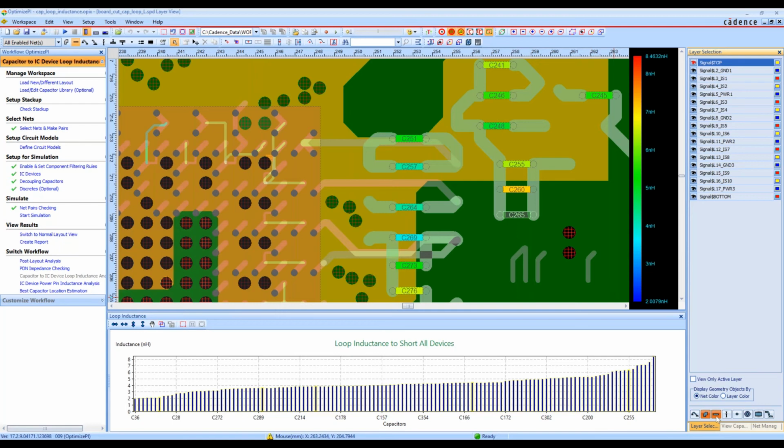So the reason that's happening, we can see, is that our ground over here is connected on one side. Let's turn the vias on too. Yeah, there you can see your connectors. And the power is connected on the other side. And you can see the loop here on the positive side has to go all the way to that via way over, or sorry, I had them flipped. This is ground over here. And power has to go all the way over to here to connect to our power. So that's a long loop, a really long loop, and therefore we have really long loop inductance.